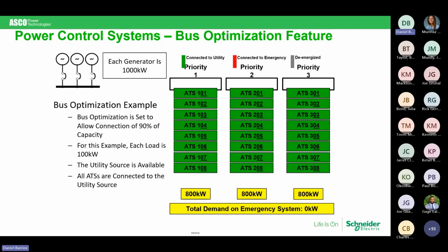What we do now is we also introduce a power meter on each of the transfer switches, and in lieu of just a plug number, the 400 kW or such. Historically it's looked at and said, yes, you told me 400, but I really know there's only 230 kW load. That's the number that we use in order to do this priority load block. This should be something you should consider and discuss with Mumtaz.